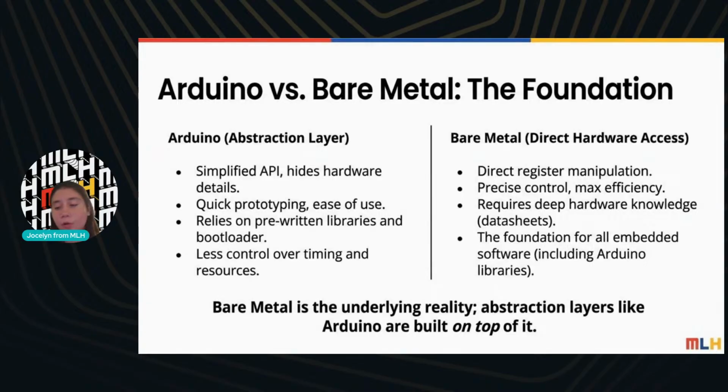The only downside is that you have less control over timing and the resources that you have. In Arduino, using your regular Arduino IDE, you are not able to manage memory, and you are also not able to control timing or the internal clock of your Arduino as you would like when you are using bare metal. Bare metal is basically direct hardware access, where you can directly manipulate each of the registers. I'm gonna explain that in just a second.